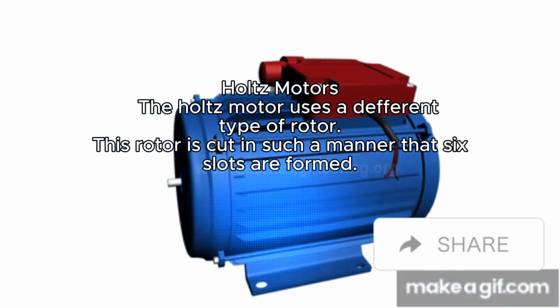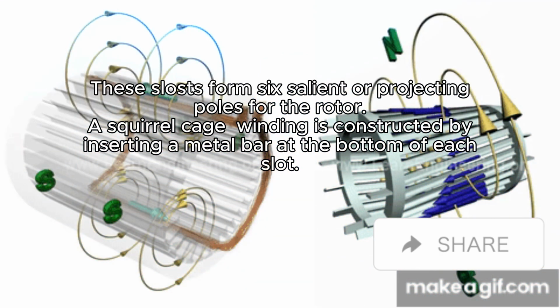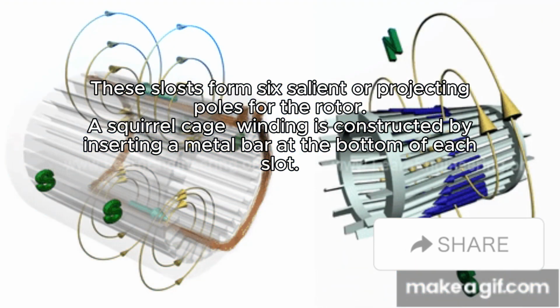This rotor is cut in such a manner that 6 slots are formed. These slots form 6 salient or projecting poles for the rotor. A squirrel cage winding is constructed by inserting a metal bar at the bottom of each slot.